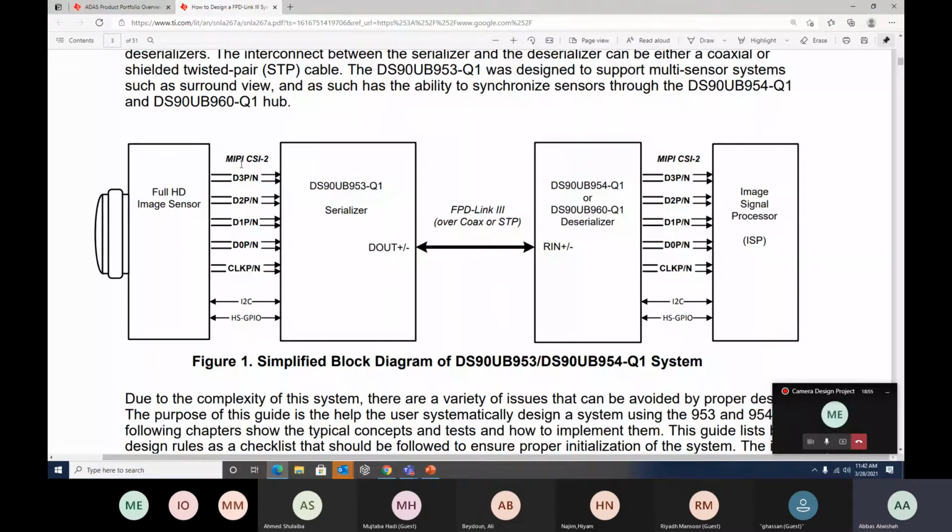It transmits it over a protocol, MIPI protocol, CSI2, I2C, and then it transfers it. Every pin here is called out for a specific reason, hardware-wise. It comes to the serializer. Serializer processes it, sends it over the link here, which is about 15 meters with 4 interconnects.